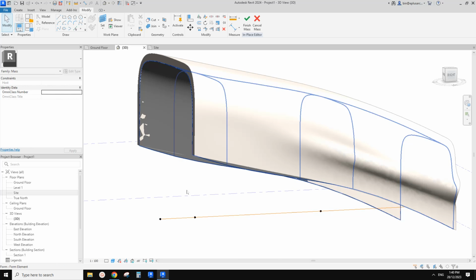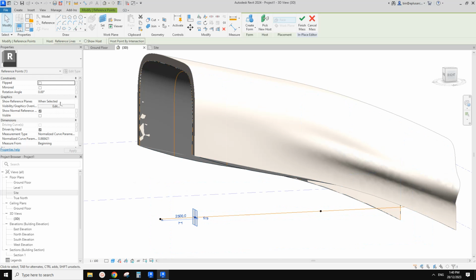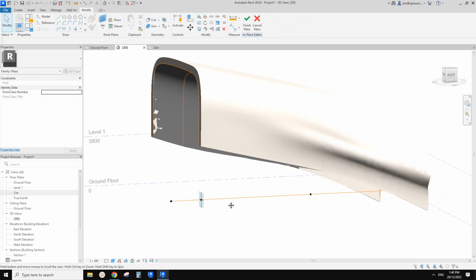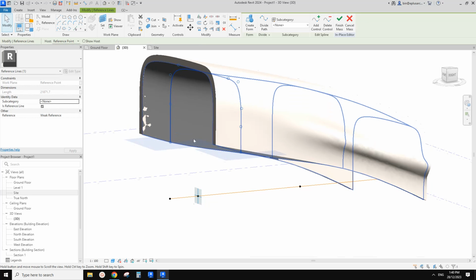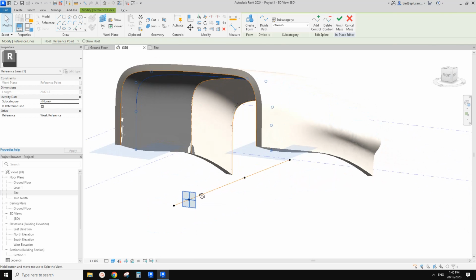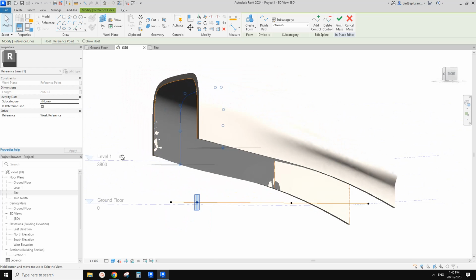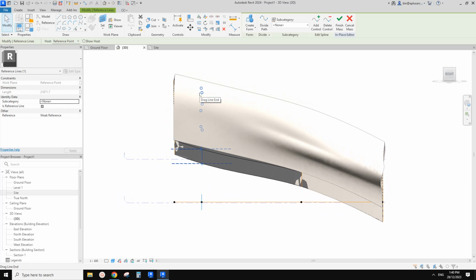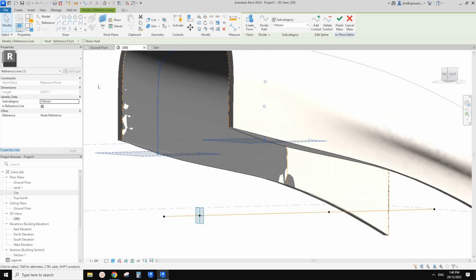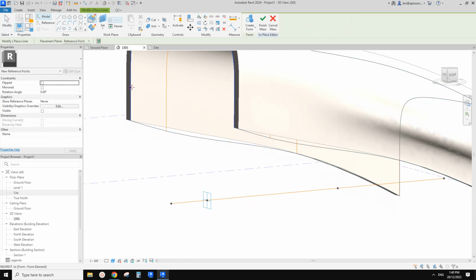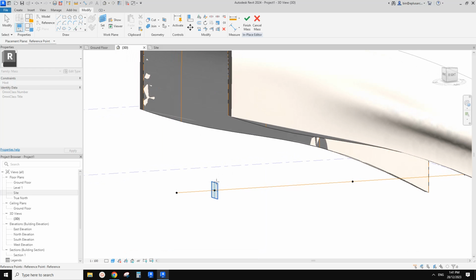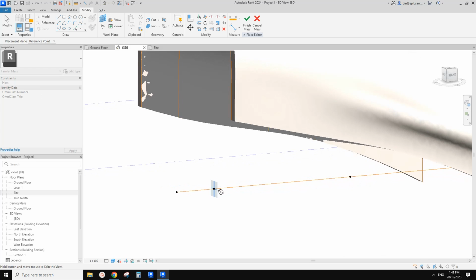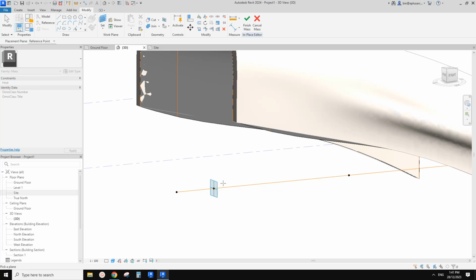What we need to do is, or maybe I'll change this one to always show the work plane. Now you can see this is the work plane where we place this profile, right? Because of the direction of this work plane, we can't rotate it this way. So what we need to do is place a point and use draw on work plane and set work plane, and we'll try to pick the horizontal, hang on, let me think. Try to pick the other work plane.